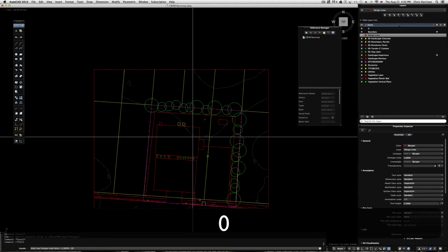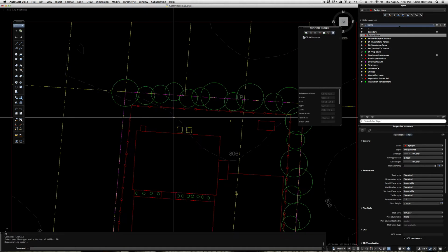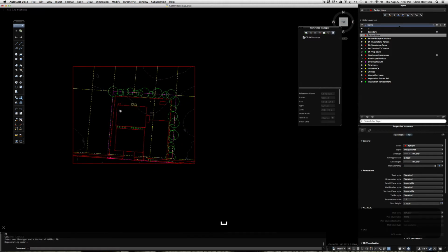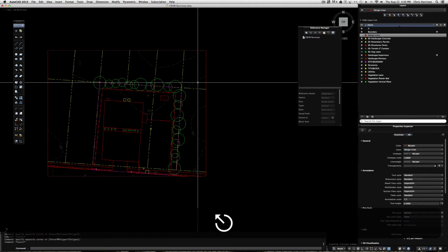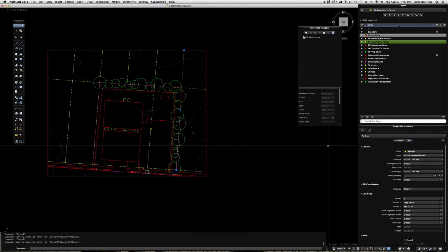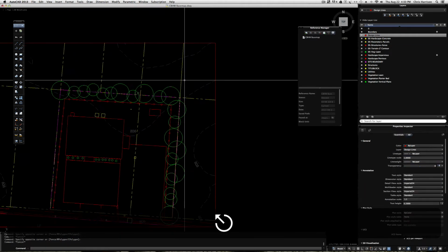and I want to change that to 20. And I did that just by going LT scale. You should be able to see my keys, but just in case, line type scale, and make that 20. And you'll see instantly that all the line types appear on your drawing. So the contours have been dashed and so on and so forth. And for instance, if I wanted to make this line type continuous, and you see the difference.